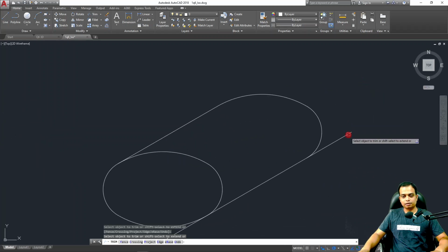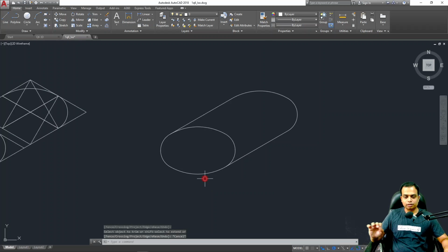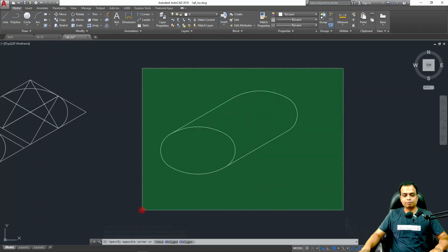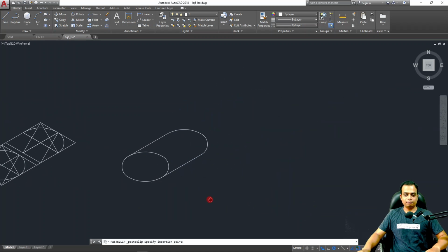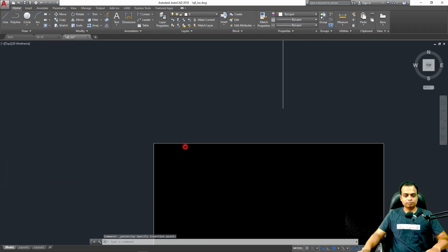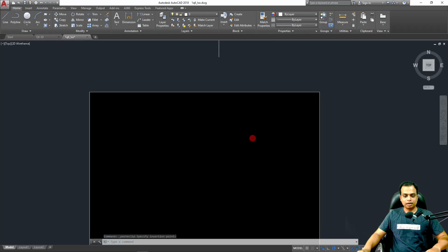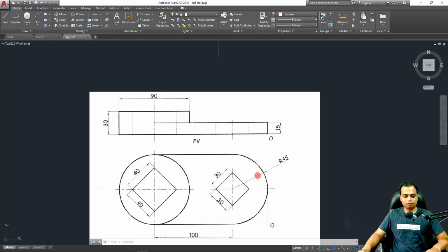Again, make sure that you create this drawing with the help of a 3H pencil, so that all the work is very light. Okay, let me copy this again, and now let me start with the modification process. The first thing that you need to observe is that this circular profile over here is having a height of 30, and then there is this profile, this sort of semicircle here, and then these straight lines. This will be lifted by a height of 15. So this is 15 and that's 30. So let me do this.